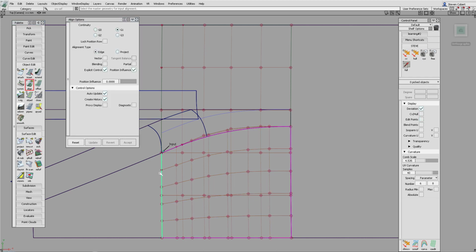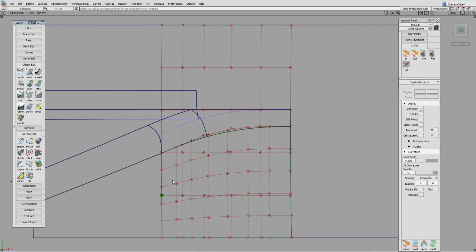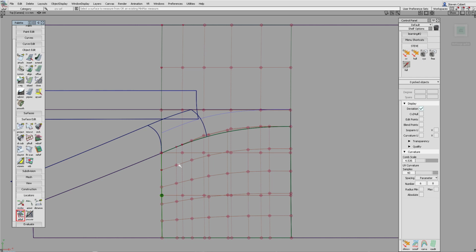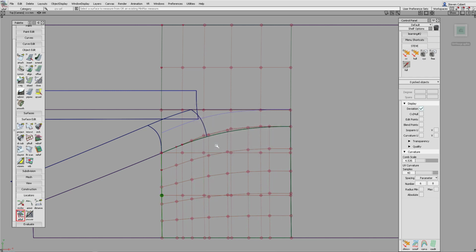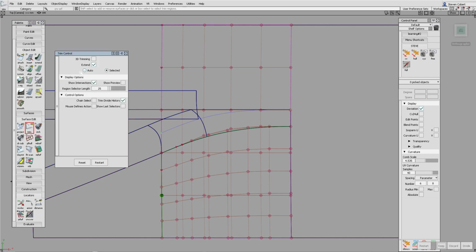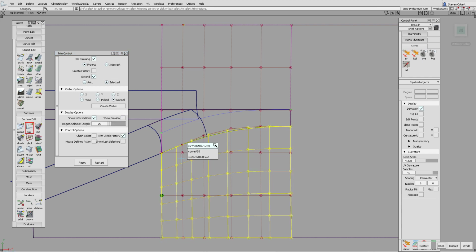We only need to use G1. G2 might change the surface too much. You can see that the accuracy of the surface is still good. Now this is a trim converted surface, so we're going to use that for construction, but we really want to keep the original surface in our final model and then throw this construction surface away. So here we'll trim the original and then template it to keep it out of the way for the moment.